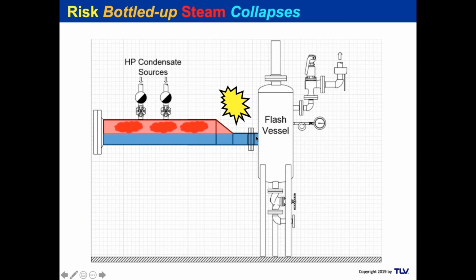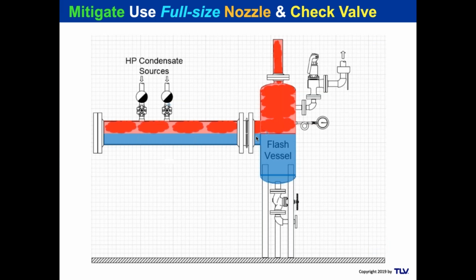And the solution is to make sure that you have the same size going in. So the two groups definitely have to know and estimate the amount of flash when they size the vessels to make sure the vessels have a big enough pipe. When you're getting a vessel that's 5 meters tall, 15, 16, 17 feet high, it isn't that much of a difference in cost to put in a bigger than you expect outlet. You can always neck up to it, but you don't want to neck down to it.